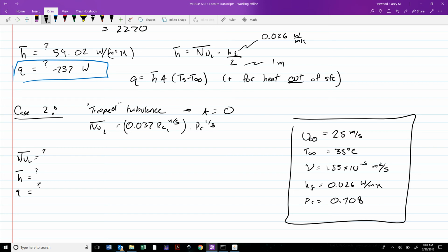Okay. Anyone have a Nusselt number? 3,049 or 3,050. That's really close. Let's go with 3050. It's cleaner. Convection is an approximate thing. I should mention that with these kinds of calculations, these correlations are fits to experimental data, and so you expect them to be inexact. How inexact depends largely on what type of flow you're looking at. For turbulent flow, for example, cases like this, 10 to 15% is your margin for error on these calculations. So it's enough to do reasonable design work.